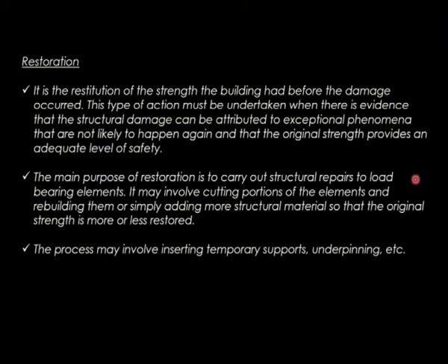The main purpose of restoration is to carry out structural repairs to load-bearing elements. It may involve cutting portions of the elements and rebuilding them, or simply adding more structural material so that the original strength is more or less restored. The process may involve inserting temporary support, underpinning, etc.